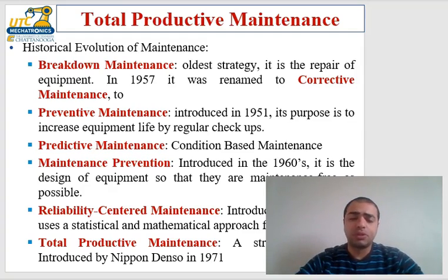Then after that was predictive maintenance. As we covered before, predictive maintenance means you use scientific methods and tools to predict when an equipment will fail, such as vibration analysis. If you remember, we talked about how everything will fail eventually from fatigue. So when you do a vibration analysis, you can predict when a fatigue failure will take place, obviously by detecting cracks and scratches on rotating and dynamic equipment.